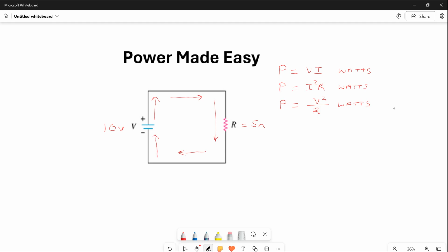And the current I, it's I total, it's the only current in that circuit, it's series. I total is equal to the total voltage, 10, divided by the total resistance, which is 5. Pretty easy. It's 2 amperes, but that's not what I wanted to show you. Anybody can do that in high school. Let's take a look at where that 2 amps flows, conventionally clockwise around the circuit.